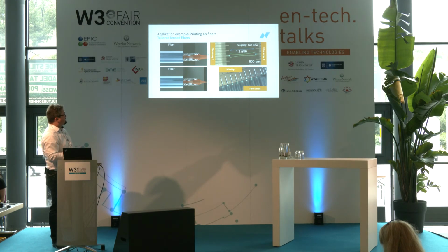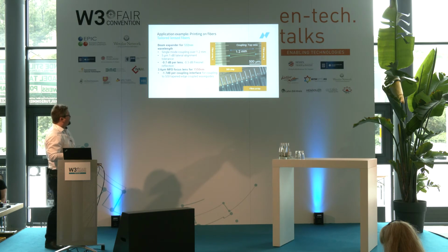Here we are looking at two lenses on fibers in a similar configuration, a similar geometry. So the light is focused to a spot here, 600 microns out, and then from there it diverges again, and it gets into another similarly shaped lens on a different fiber array. And in the bottom situation, we're looking at a tightly focused spot directly coupled into a waveguide on a chip. And we characterized both those situations.